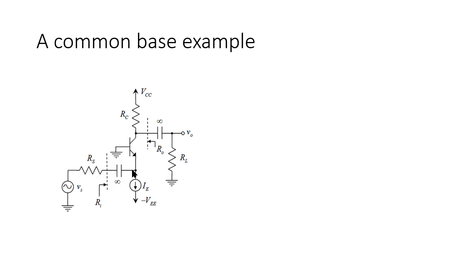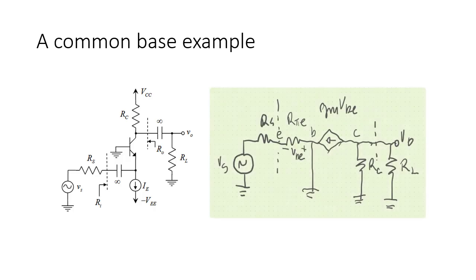In AC, that circuit would look like this. Vs, our source, there. They are connected to the emitter. What happens to this source? It's DC. So in DC, there is an open circuit between the emitter and ground. So it is not there. It would be between the emitter and ground, but it's open. It is not there. And then we continue into the transistor.